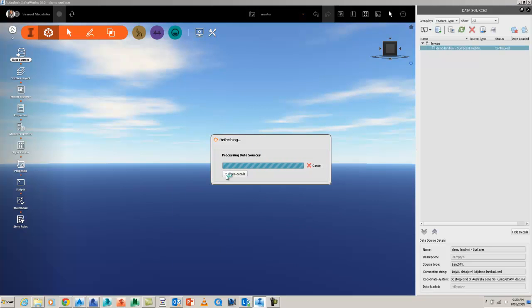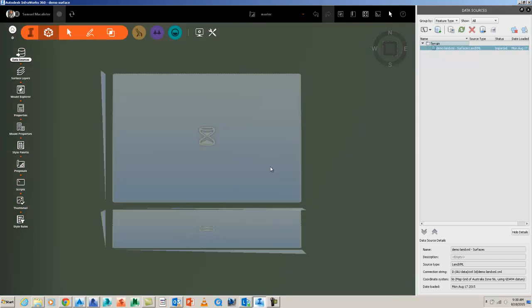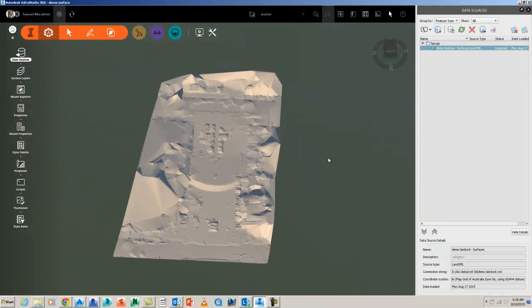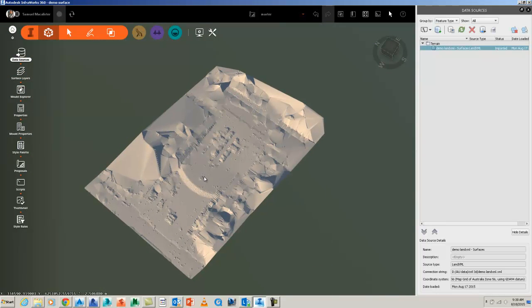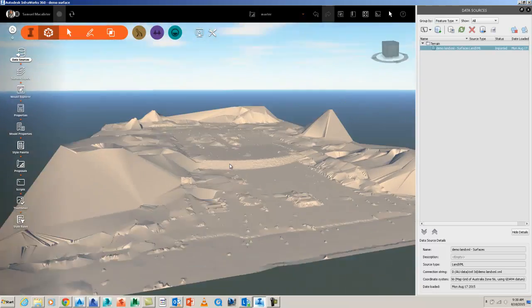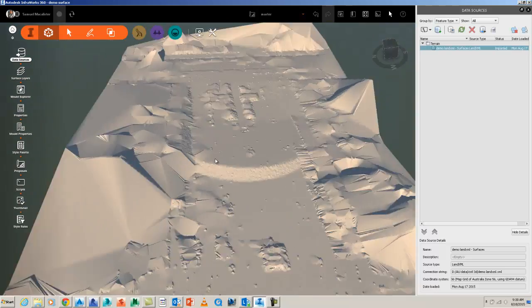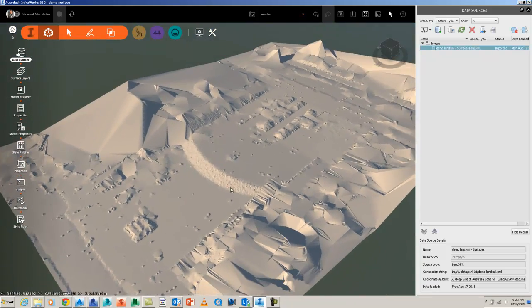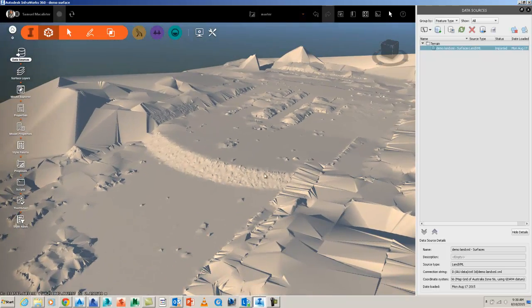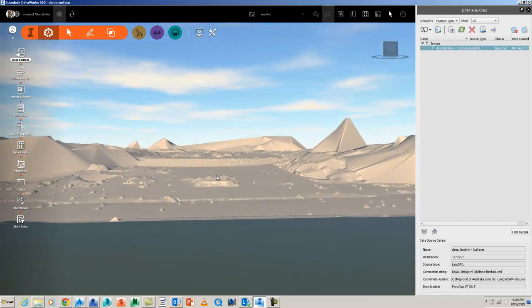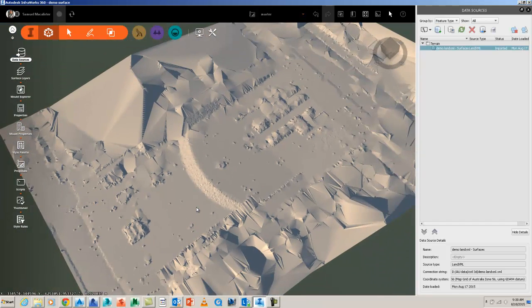Everything you need to do in this application is close and refresh. You can see it's importing, and now it's bringing in that information as a surface here, and it's in the correct world coordinates. What you'll see here, as I mentioned, is that it was created from a laser scan. I could have tidied this up a little bit more, say in Site Designer with some building pads. It's just a rough demo. There's a bit of information here, like the stairs, that's just created into a rougher surface. But it's a good starting point for doing sketch design.